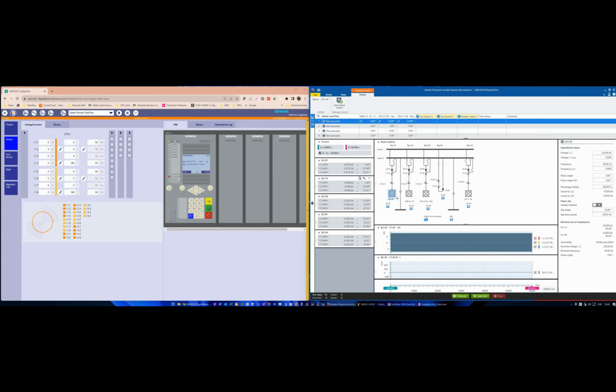For example, my bay AY has this current with this angle, -7. And my bay CX is at the same angle. So we can conclude that the current is in the same flow in these two bays. And this bay, DX, is positive at 108, so this current is in the opposite direction.